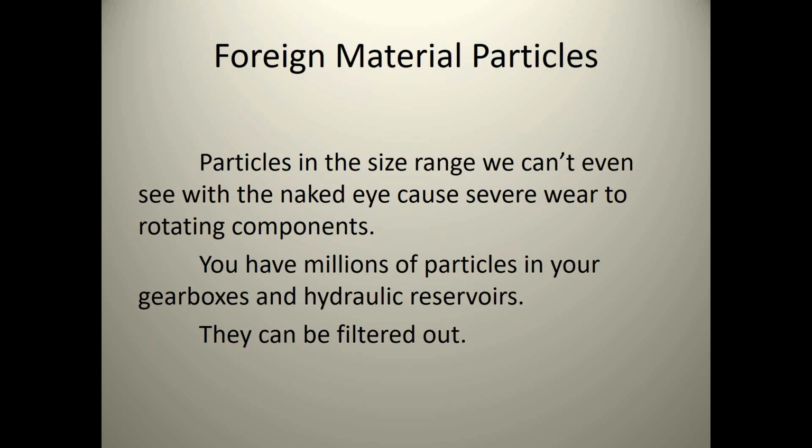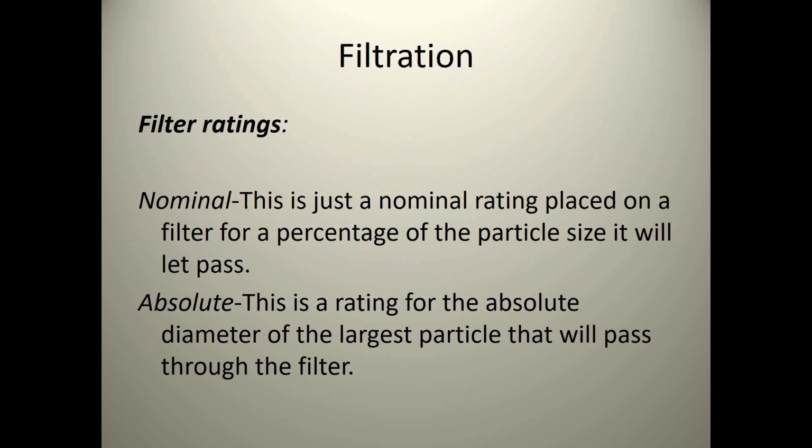If you take a hydraulic system, in a standard hydraulic system you're going to have millions of particles, and they have to, at some point, be filtered out. Now, one of the things I've noticed is that most hydraulic systems manufacturers sell you have filters on there, but the filters are not beta rated. Some of your old hydraulic units around your plant with the little small filters on there, those filters aren't much better than a car filter. They're just a paper filter. They'll take some big stuff out, but they don't get that small stuff out that's going to cause damage.